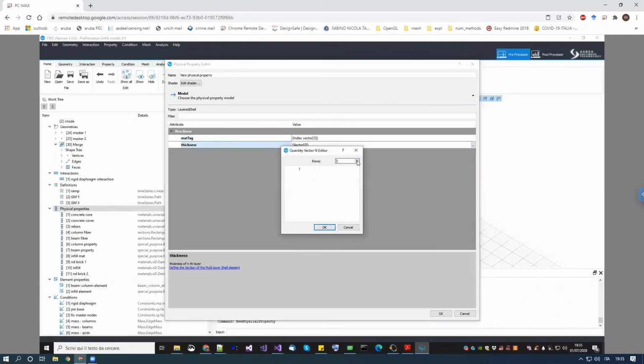Now the only problem is that this is fine as far as you can assume that there is no slip between the 2 layers of bricks, okay? Instead, if you want to model that behavior, a shell is not suitable. So you can either do it with solids, and you can use our material model for doing that, or you can use 2 different shells with some nonlinear connection in between, okay? So keep in mind that when you use a shell like this, you can have this kind of composite material, but the assumption that the cross-section will remain flat is still there. It is inside the kinematics of the shell. So you cannot do that if you expect the two layers to slip from one another, okay?